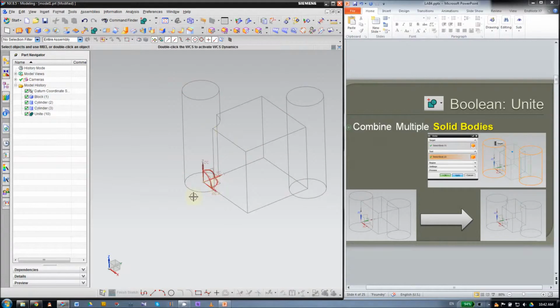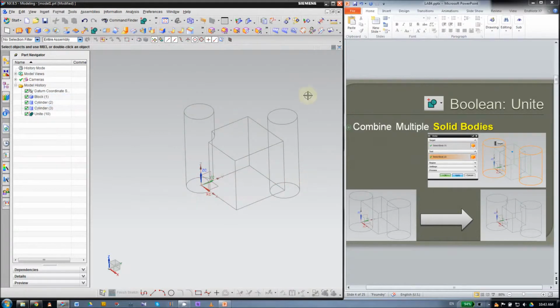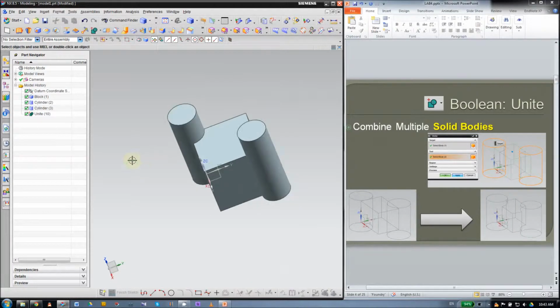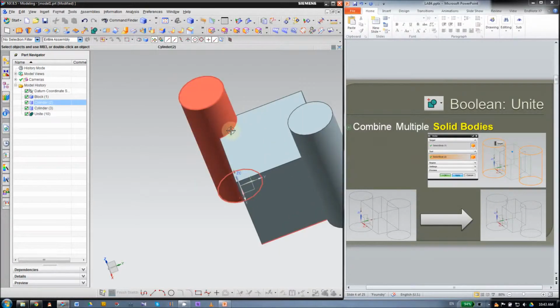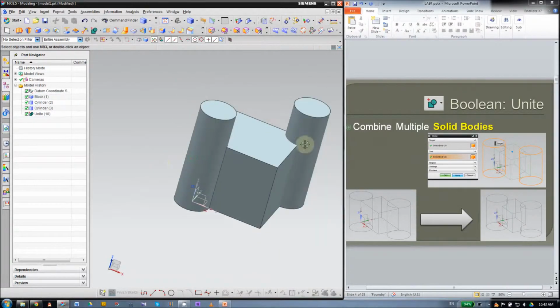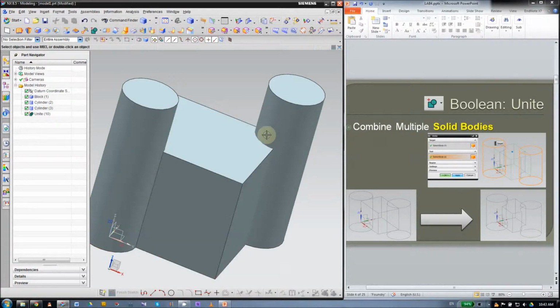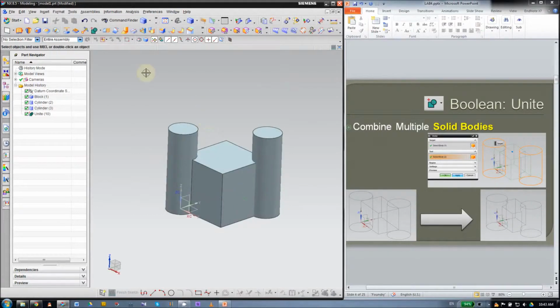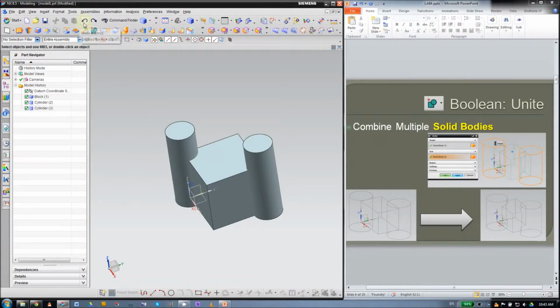You can see clearly the wireframe changed after you unite these two pieces, and on the right side they're still separate. The same goes for the shaded view, where you have this solid line here. Because they're separate, you don't have a solid edge. So that's the unite command, and I'm going to undo this, and we'll go to subtract.